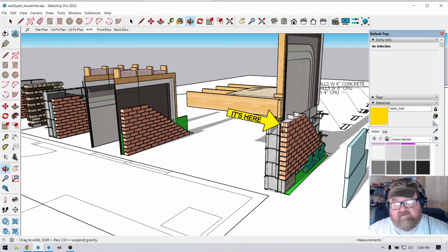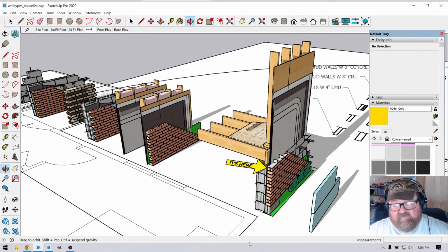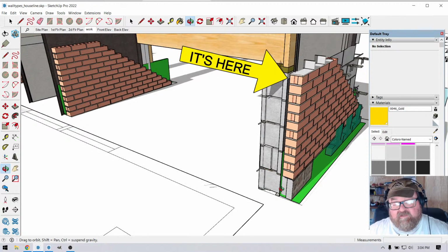Okay. And again, it goes back to sequence, right? Because now, if we do have a brick ledge, we have to tell the block mason that where these little nails were put is the house line, not the face of the brick. Okay, that's added to the house line.